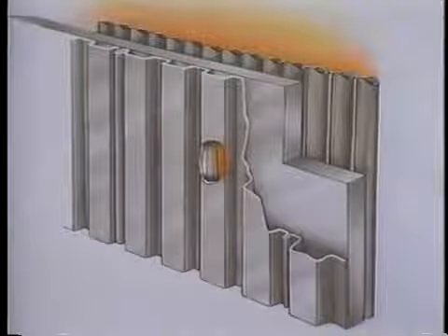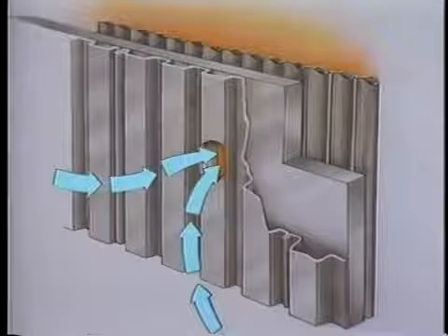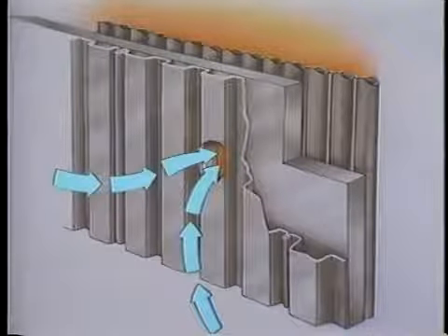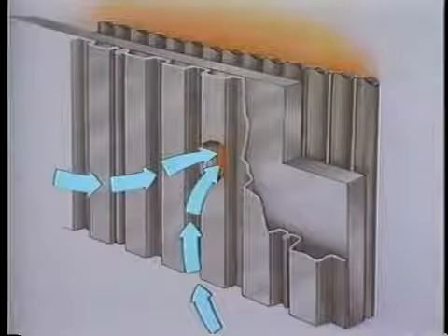Balanced draft boilers, for example, operate under a slight negative pressure. For the most part, any leak in the casing will draw air into the boiler. Air leaking into the boiler through the casing can affect the combustion process, the operator's ability to maintain a proper boiler flame. If this is not the case, however, the operator can continue to operate the boiler until a shutdown can be scheduled. If combustion conditions cannot be properly maintained, the unit must be taken out of service immediately.